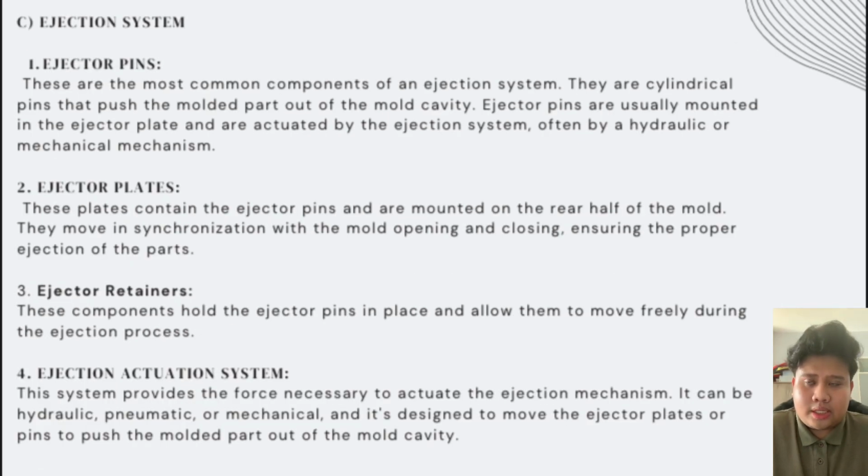Ejector system. First is ejector pins. These are the most common component of the ejection system. They are cylindrical pins that push the molded part out of the mold cavity. Ejector pins are usually mounted in the ejector plate and actuated by the ejection system, often by hydraulic or mechanical